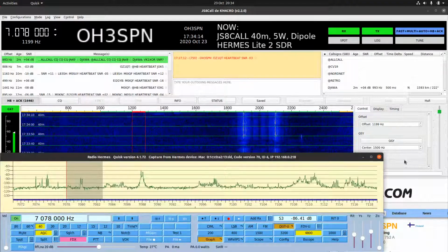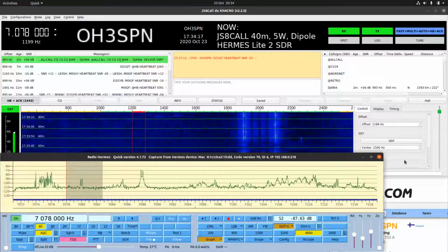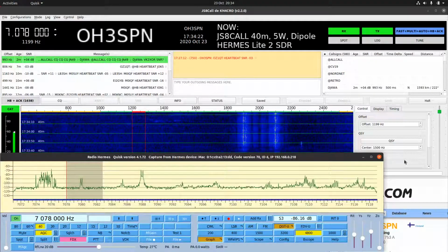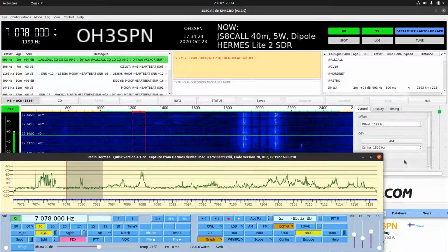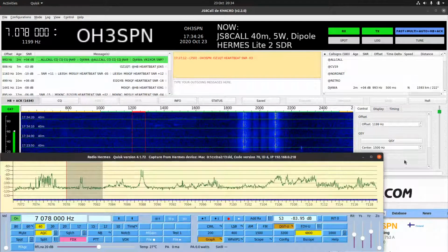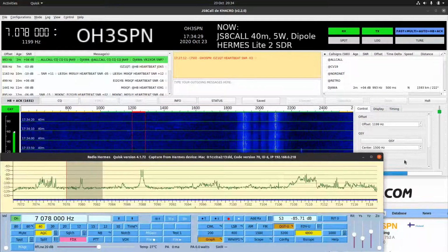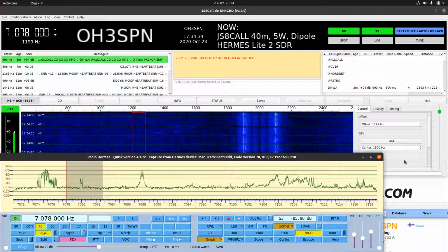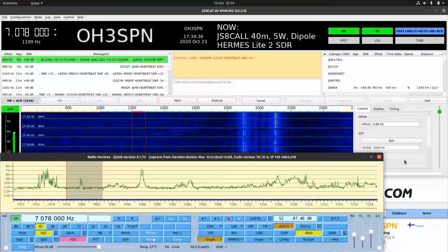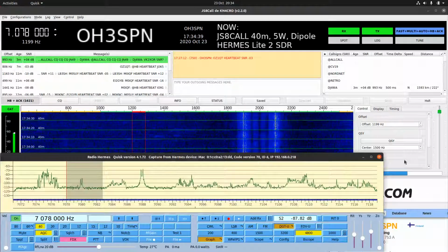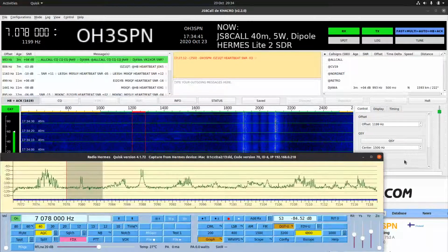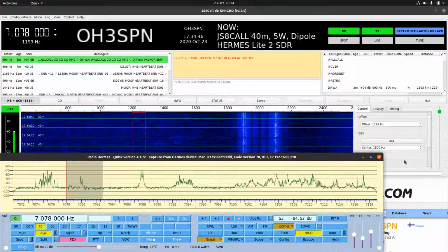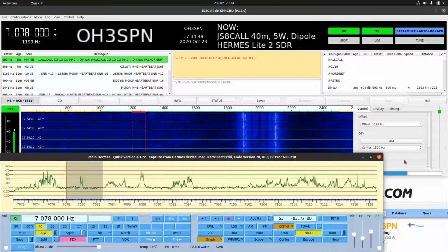It's got MIDI control of CW, which is really responsive. If you're doing 30, 40 words per minute, maybe you'll notice a few microseconds lag. But if you're running the sort of speed I run, which is 10 to 15 words per minute on a good day, it's perfect. And the filters in Quisk are really, really good. And I recently bought an ICOM 7300. The filters in Quisk are actually better. And working with the Hermes Lite SDR2, the front end appears better.